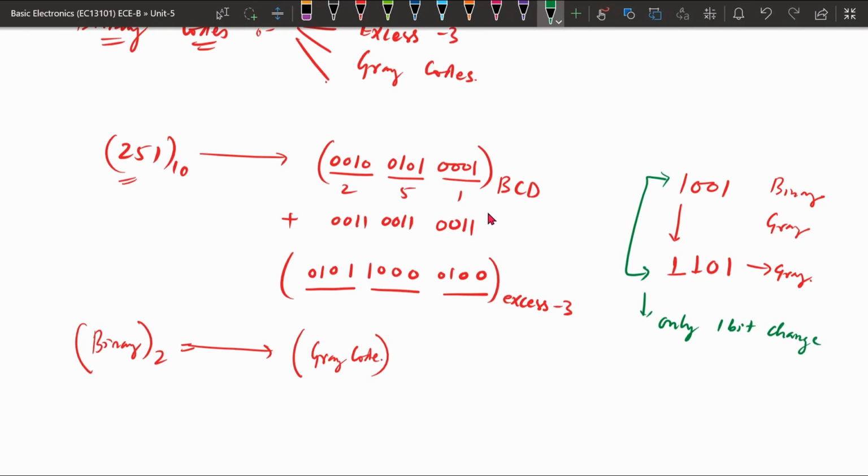If we use the gray code, it reduces the power dissipation, or it basically avoids large changes. Suppose there is 0 0 0 0, or 0 0 1 0, or any representation, and the next is 0 1 0 0.